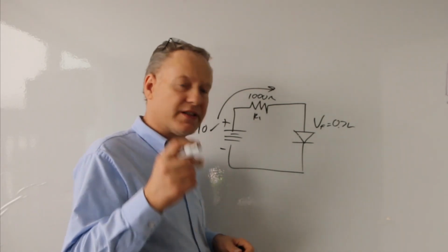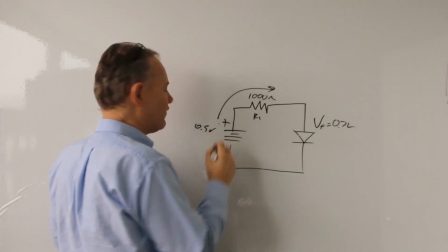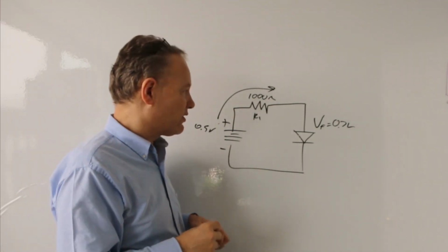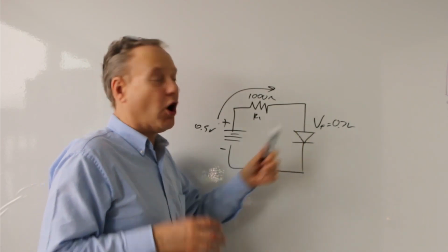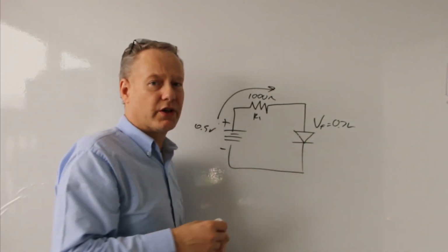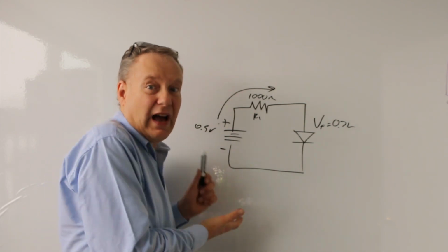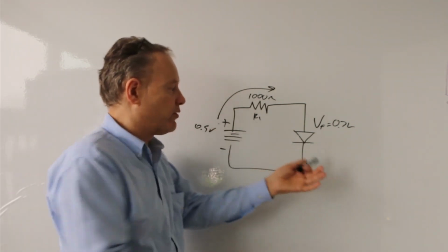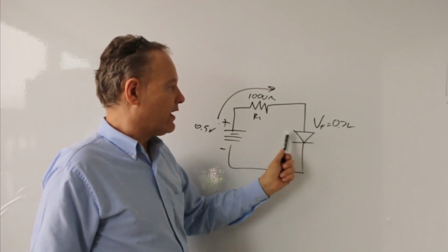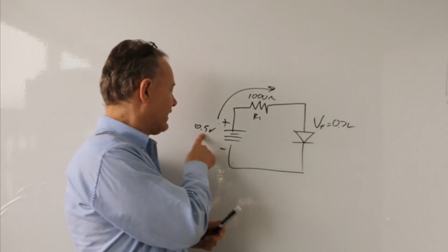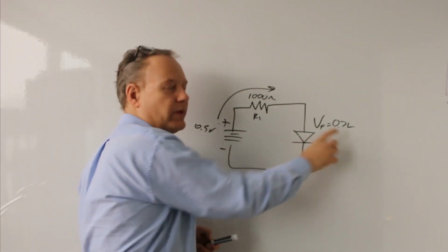I guess the only thing is this. If I were to change this down to 0.5 volts, then essentially this guy is not going to open up. It's not going to allow any current to go through it. Actually, the voltage drop across that will still be 0.5. So no matter what voltage you put on here, you'll see it. And as soon as you get to 0.7, it will stay at 0.7. And if I kick that up to 10 or even 0.8, that'll still be 0.7.